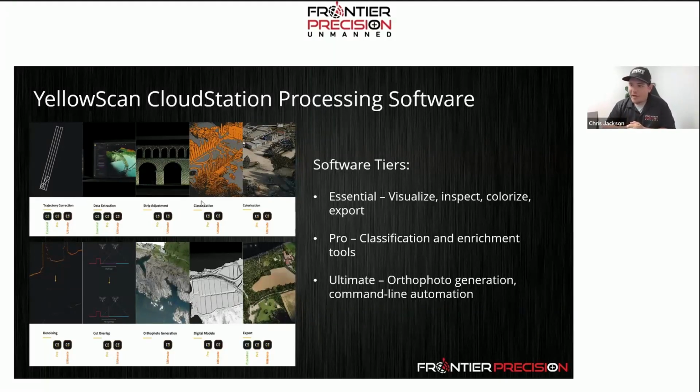Denoising, cleaning up our point clouds. The cut overlap tool is a really nice feature to have, especially for LiDAR data, since it can get dense pretty quick. If you're out in the field for an entire 8 hours collecting, you can easily be taking 100 gigabytes or more back with you to the office. Obviously, we want to work with as small of data sizes as possible, to make it easier on our machines.